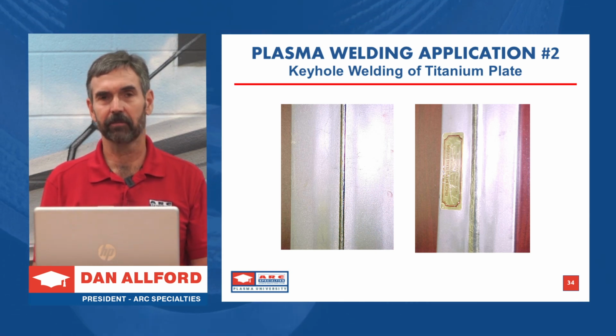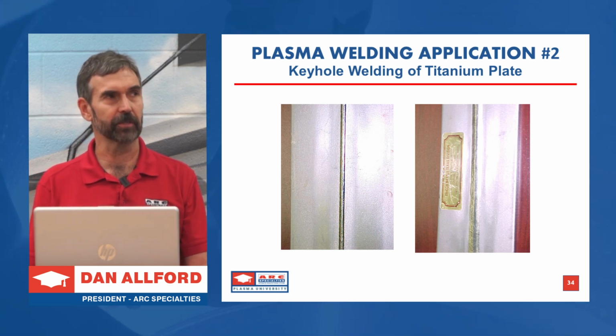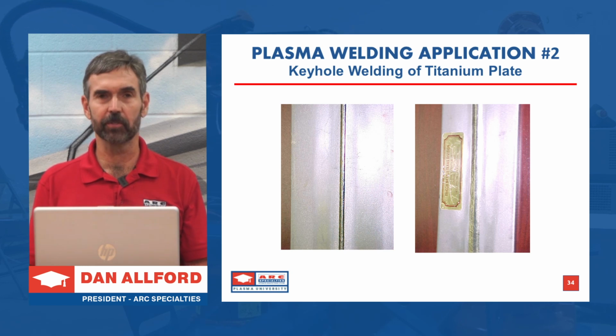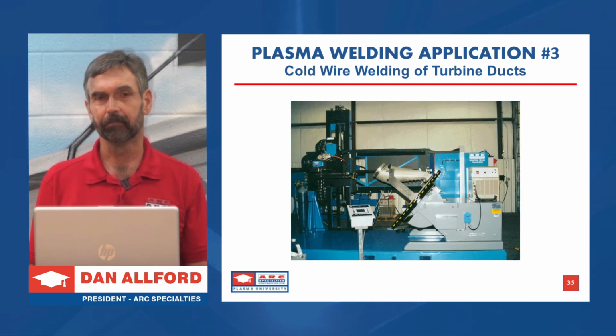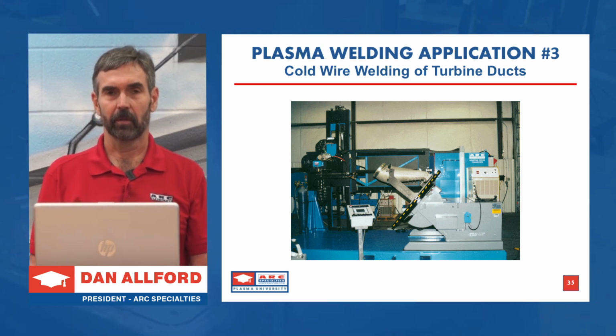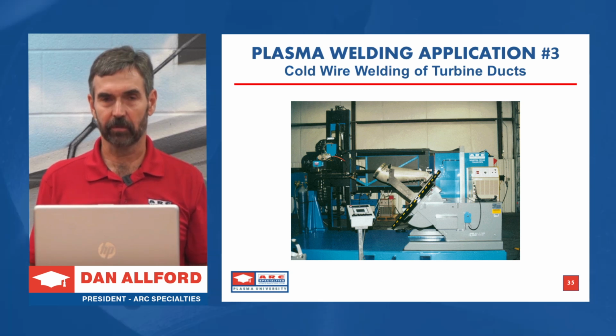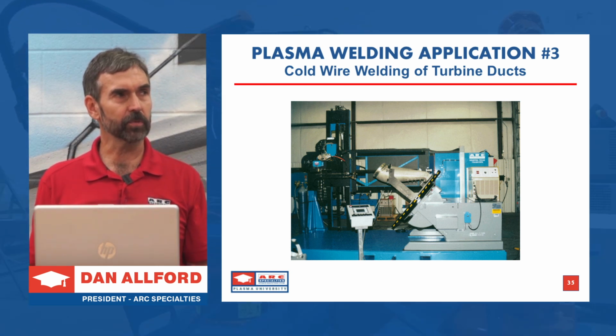Since titanium is a high value item, they're willing to spend the time to give me the good joints that are necessary for keyhole welding. But if you produce these good joints, you can weld much more efficiently because we have zero groove volume. If you want 100% penetration all the way through a part, you're limited to two techniques. You can either keyhole weld, like I showed you just before, or you can melt in. And so this was a melt-in technique.